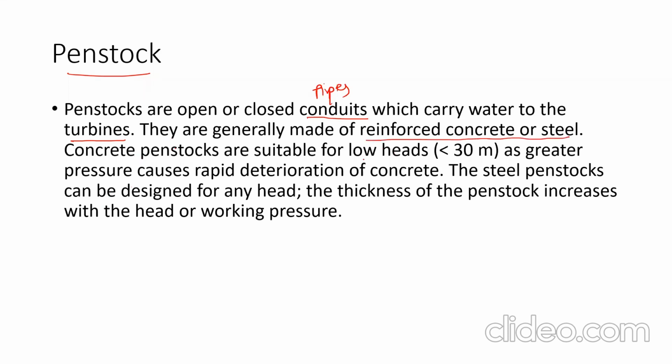Concrete penstocks are suitable for low heads. Low heads means low erosion is there, and in that case concrete penstock will be used. But for large head, when the reservoir capacity is very high, the pressure created by water on the penstock will be high. In that case, concrete penstocks cannot be used. Instead, steel material is used to design the penstock. And the thickness of the penstock increases with head or working pressure.